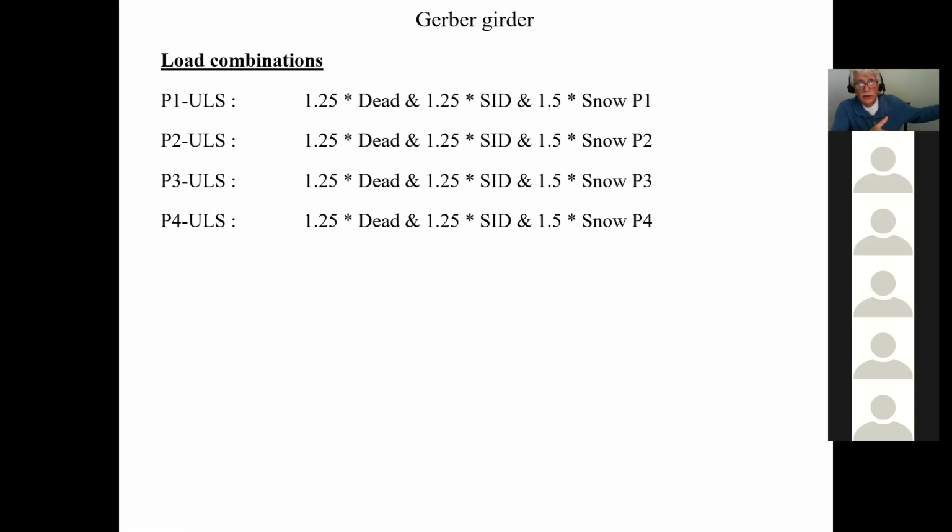You put in all these specified loads, and in the combination, this is where you put the load factors, based on the limit states design load factors. We know that for snow, it's 1.5. And when you combine the dead load with a variable load, we know that's 1.25. That's why we have 1.25 here and so on. Is that clear to everybody?